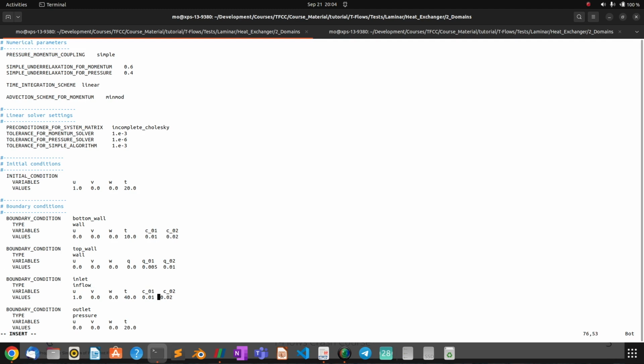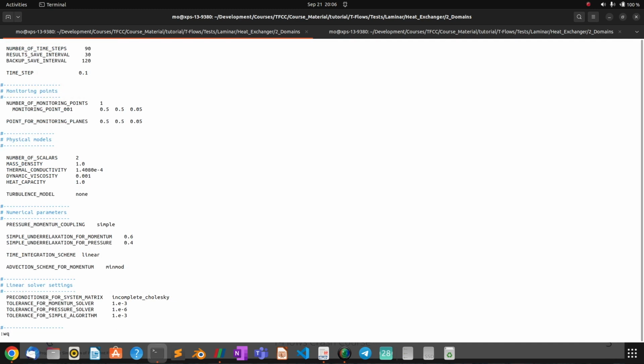That's good. The only thing that I wanted to hint about now is that the control file is very flexible, right? So you can add any parameter, any value, any keyword in any part of the control file, except this part, because it has to identify a boundary condition. Otherwise, if you put these values in the middle of the control file, what are they? So if you want to specify a boundary condition, it goes exactly by the order: boundary condition name, boundary condition type, and then the values. That's it. Once we specified this, let's go.